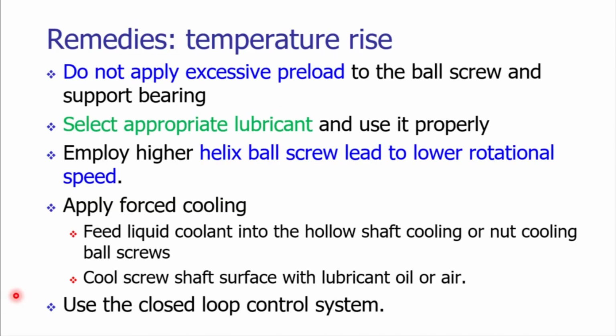How can we mitigate the temperature rise? How can we solve the problem of the temperature rise? The temperature rise can be reduced by reducing the excessive preloading to the ball screws and support bearings. So if you are applying more preload on the ball screws, more heat will get generated. So there has to be a balanced or optimum value of the preload that is to be applied on the